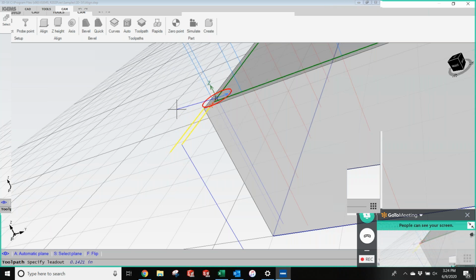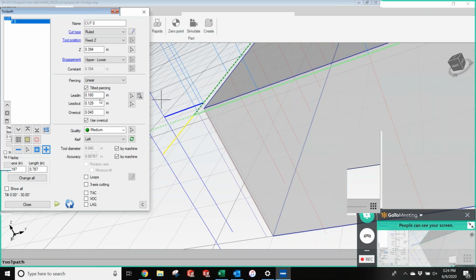For the lead out, I'll put a little lead out on here for right now. But if I change the lead out length to 0, and in this case we do 0 overcuts, and we put a negative lead out length in here, turn off the lead out. If you put a negative number in here, then that tells the jet to stop earlier.